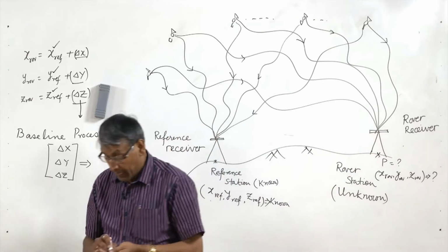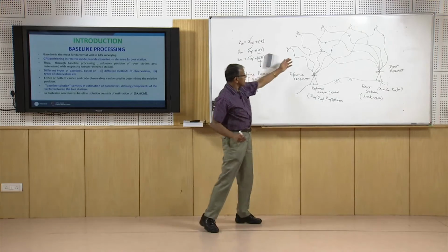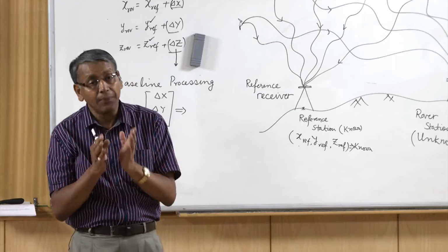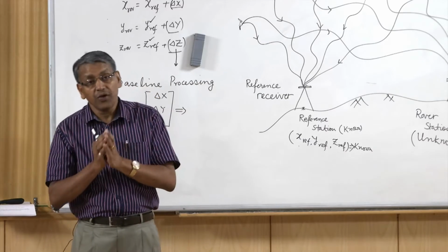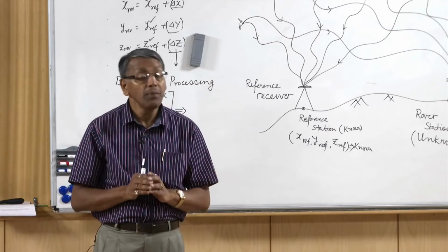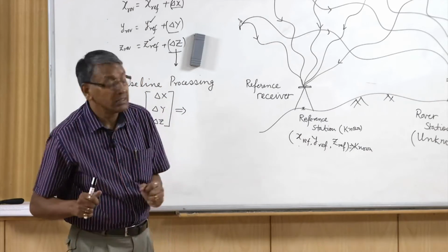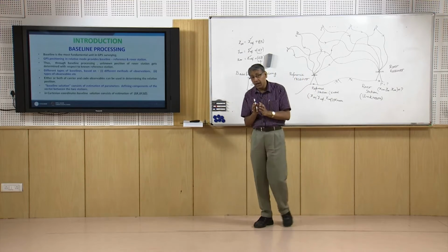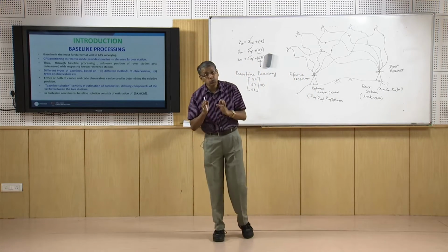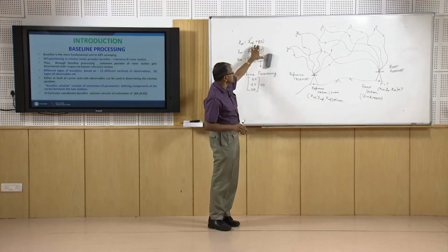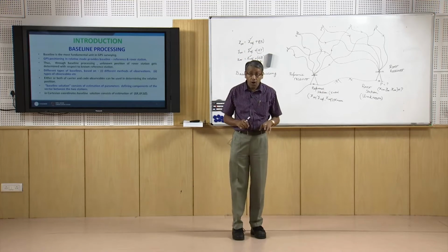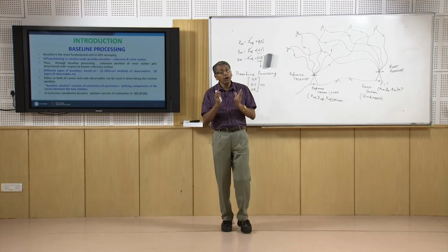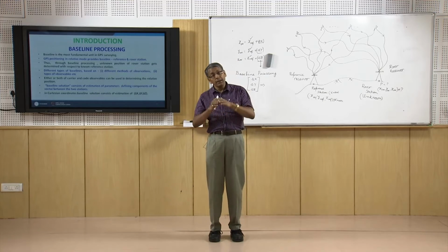As you know, in these signals we have 3 types of carrier phase observables and 5 types of pseudo range observables. All these individual components may be used to find the baseline parameters, either individually or in multiple ways.